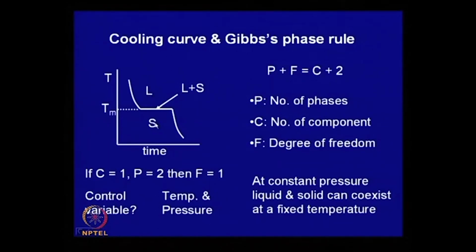So, in case of solid, we have seen that the maximum coordination number in metal that you can have is 12 in face centered cubic, whereas if the same metal, which has a face centered cubic structure in solid, gets converted to liquid, possibly you will not have 12 as the coordination number. The coordination number will be less than 12, but nevertheless still quite high, maybe 10, 11.